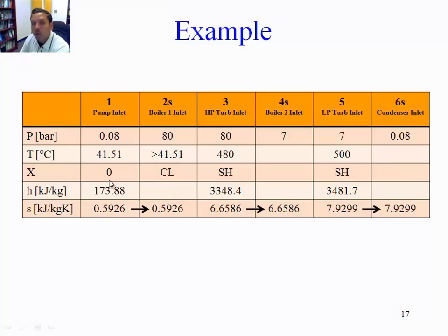Remember that we are going to approximate the power generated, or the power used in the pump, as the change of pressures times a specific volume. The specific volume of liquid water is 10 to the minus 3 meter cubed per kilogram.